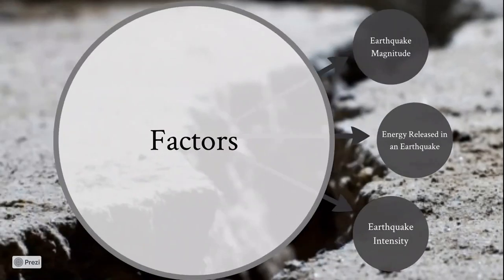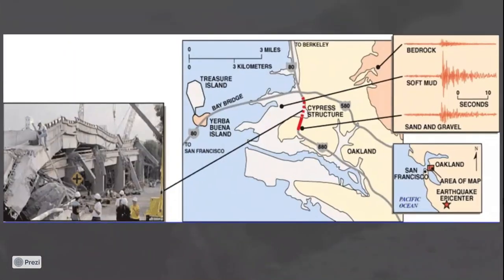And finally, the earthquake intensity. Whereas the magnitude of an earthquake is one value that describes the size, there are many intensity values for each earthquake that are distributed across the geographic area around the earthquake epicenter. The intensity is a measure of shaking at each location, and it varies from place to place, depending mostly on the distance from the area. However, there are many more aspects of the earthquake and the ground shaking that affect the intensity at each location, such as the direction the earthquake is in, and also what type of surface geology is directly beneath you.